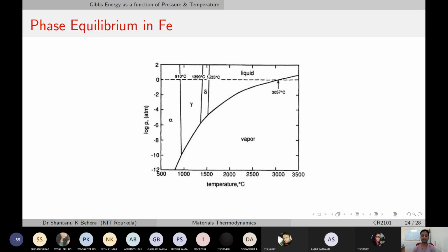So that's one of the reasons it's slightly onto the right. It's less than 90 degrees, this line, right? So it's like any other phase diagram that you'd find in materials, that solid to liquid transition always goes for higher volume or lower density, and since solid to liquid transition is always endothermic, mostly this line is onto the right.